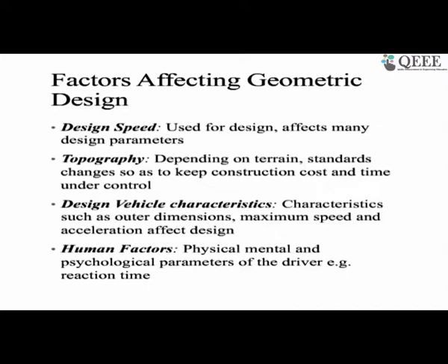Each of these trucks operates differently. So if you ask a multi-axle truck to make a turn, it will take a wider radius. So if we are designing a facility where vehicles are required to turn, and that facility is going to be used by a multi-axle truck, we need to design for that particular vehicle. So that becomes our design vehicle.